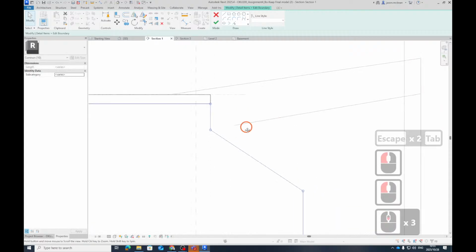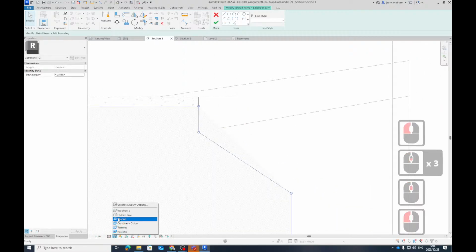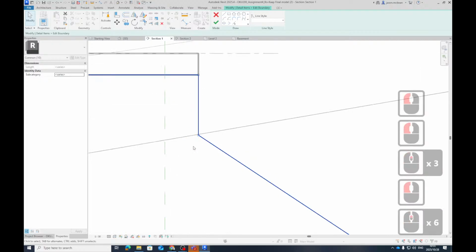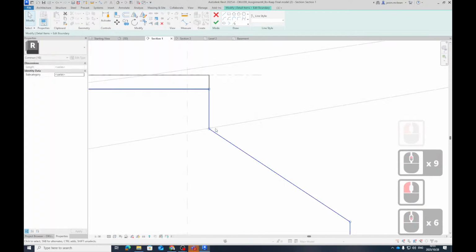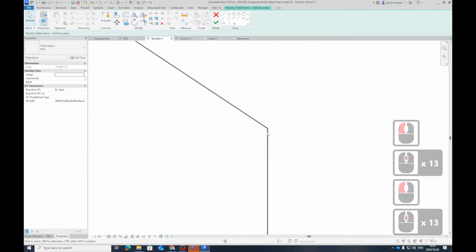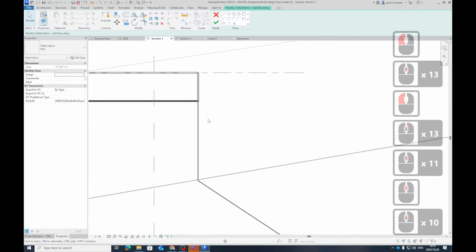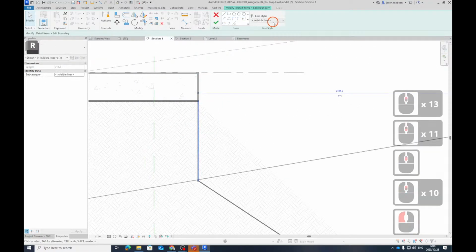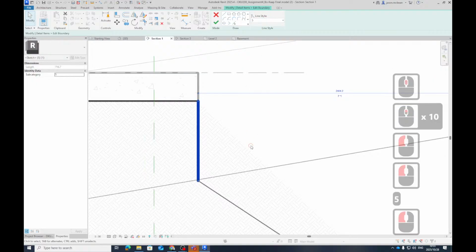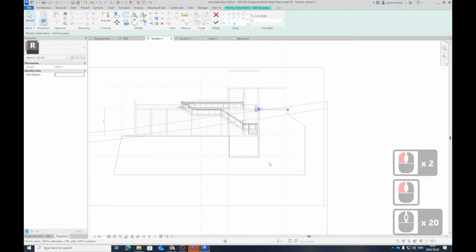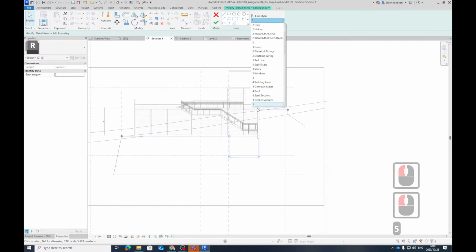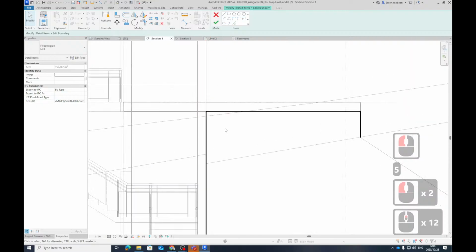Now I need to kind of guess, you can switch on wireframe mode so you can see through an object. So wireframe, this will stop somewhere. Then I just need to trace this. You'll see it will change now when it's invisible lines. Just make sure that's line weight 5 or 6. Don't know why that didn't change. Anyway, select all of that quickly. It's very quick. 5 on your keyboard jumps you to the categories. Those will be nice and thick now.